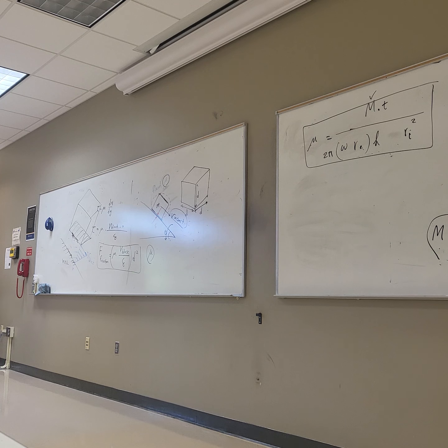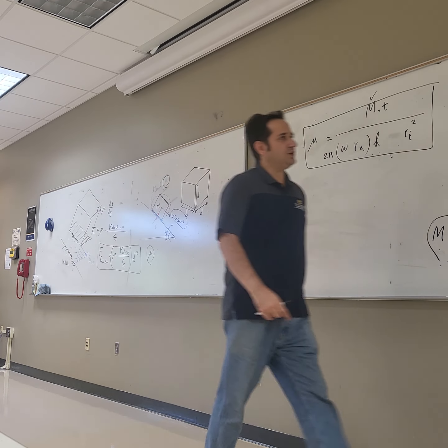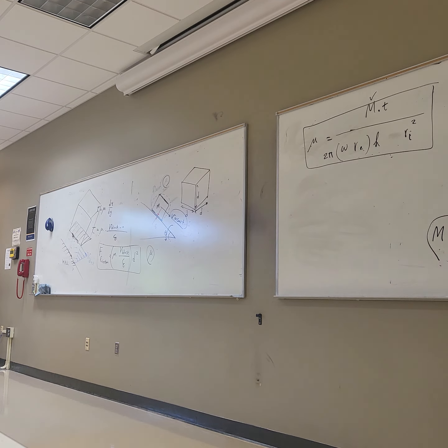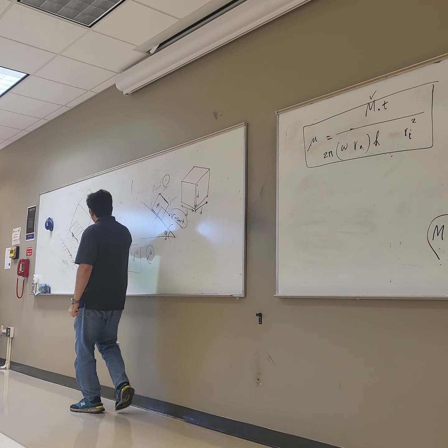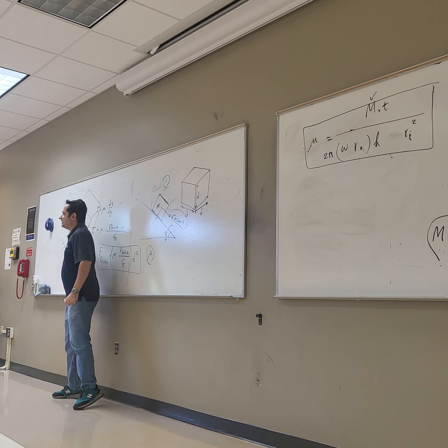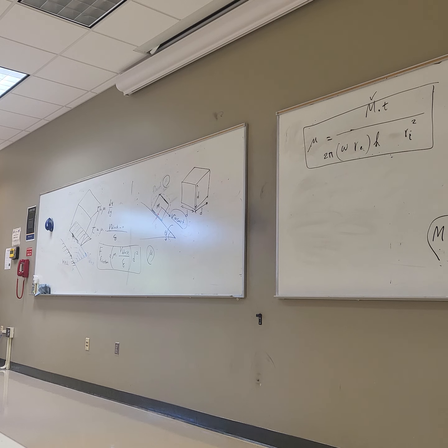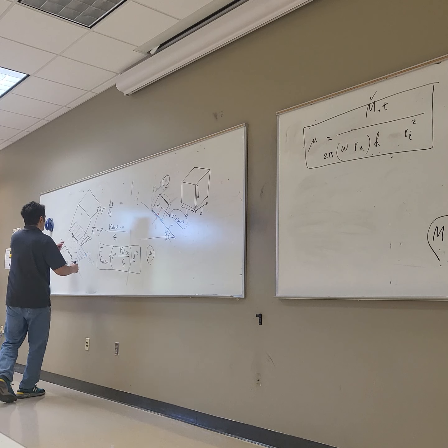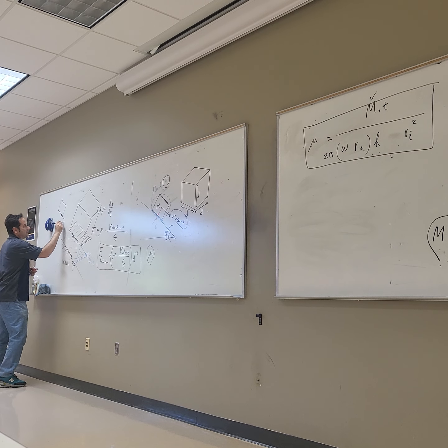But you may ask, how can I measure the force on the block? Here I had a little fixture that could measure the torque because the inner cylinder was fixed. How can I measure the torque force on this block? This block is free to go down. The answer is, you just do the 5 steps again. If you take this system, FBD, you get this friction right here, F friction.